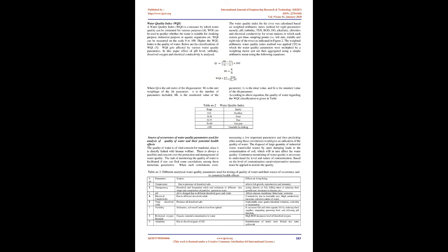Methods for physico-chemical parameters. For analysis of parameters, the water samples will be preserved at the collection site by adding appropriate reagents and brought to the laboratory. Spectrophotometric work will be performed using a Carl Zeiss spectrophotometer for analysis of nitrate, phosphate, and fluoride etc. 14 Determination of total hardness, TSS, DO, BOD, chloride will be carried out by the standard methods.